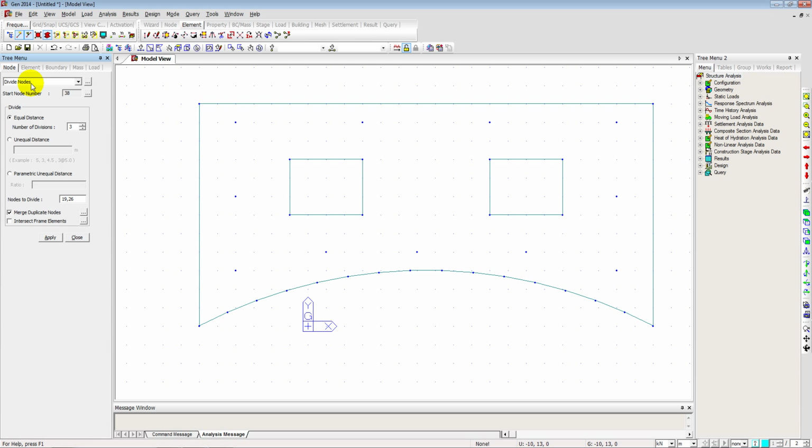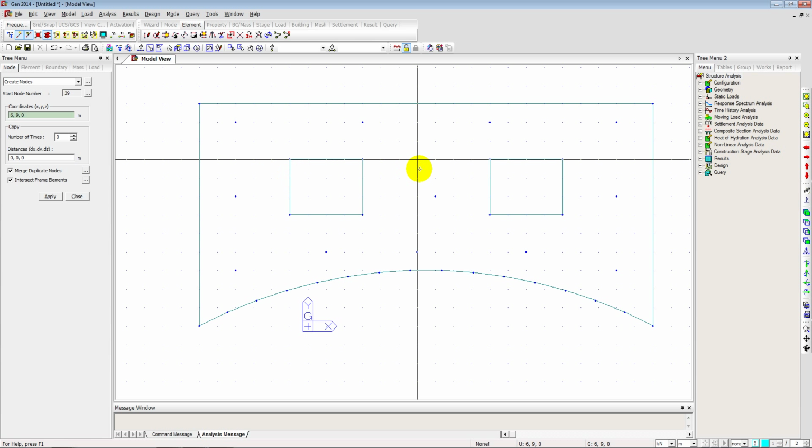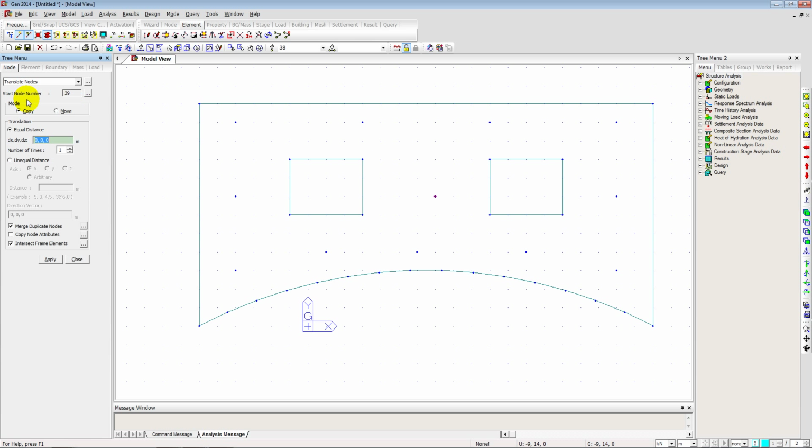So now we've got all of our columns and everything in place, and our shear walls, and also the layout of the floor. I just want to create one more nodal point. So I'm just going to move that node 0.5 meters because I want it slap bang in the middle, so visually it looks correct. Same again, just the translate function, to move it 0.5 meters in the X direction. There you go, it's just moved straight to the middle now.